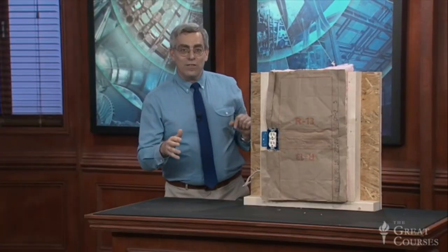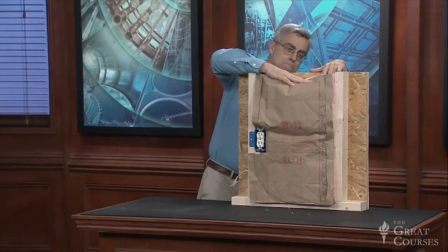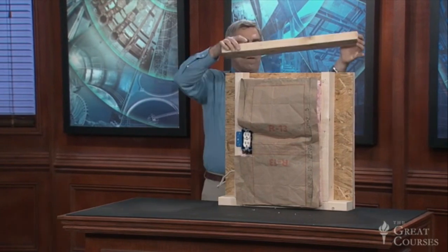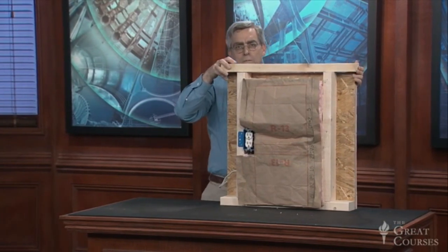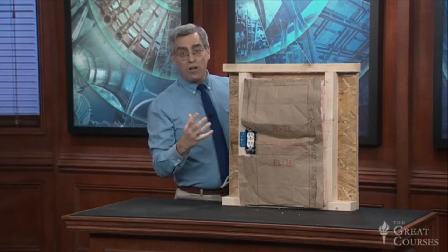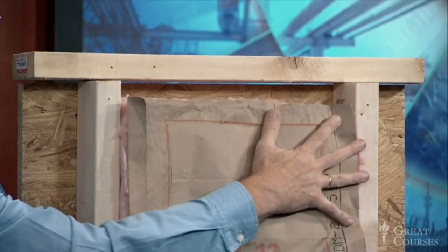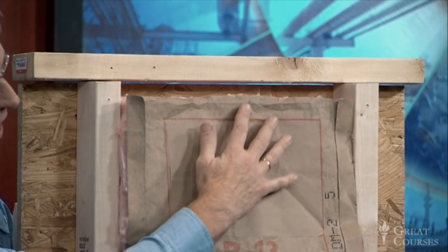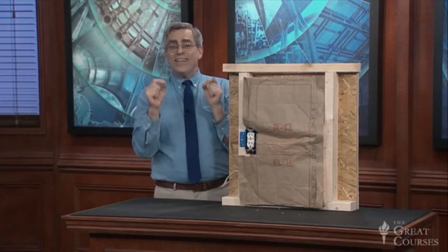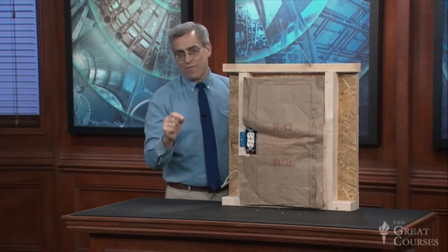Unfortunately, many contractors don't exercise this level of care, and the insulation's thermal resistance is compromised as a result. Just a 1/2 inch gap between the fiberglass and an adjoining stud or top plate can cut its effective R value in half.